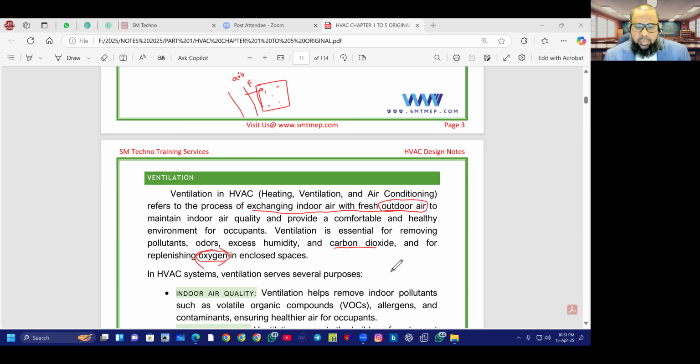Yes, sir. Apart from this, when you take this fresh air or outside air in, what will happen? You must exhaust some air outside now. For example, if I'm supplying say 300 CFM. If you're a beginner and don't know CFM, remember it's cubic feet per minute. It's a flow rate of air, volume with respect to time. Okay, so some amount of air I'm introducing inside this room.